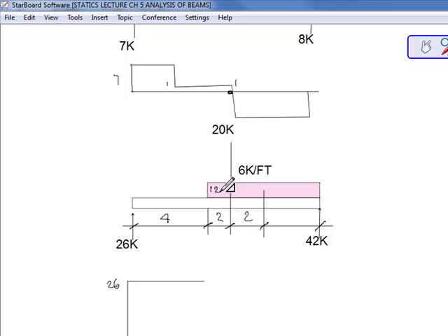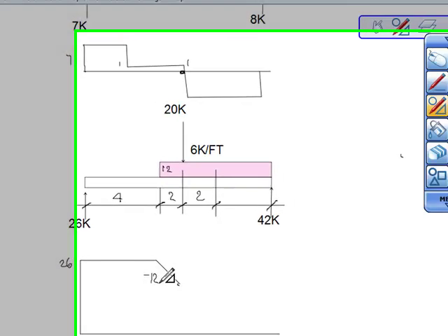So then we'll drop down, we'll angle down 12 until we hit this line. So we get about even with that. And then I'll say that equals minus 12. Then we're gonna go, because there is a point load there, we're gonna go straight down 20, right? Y'all agree?